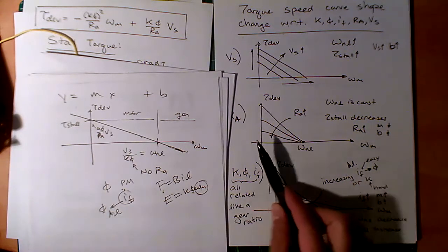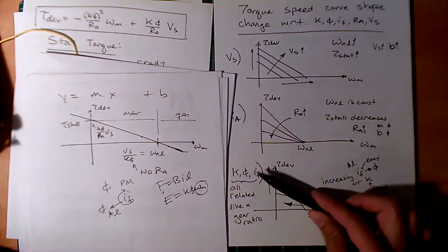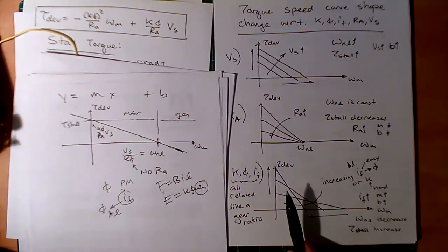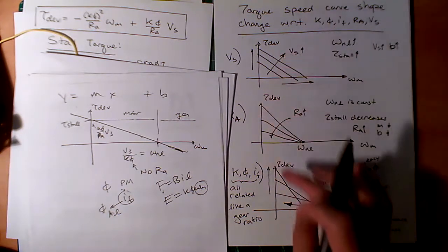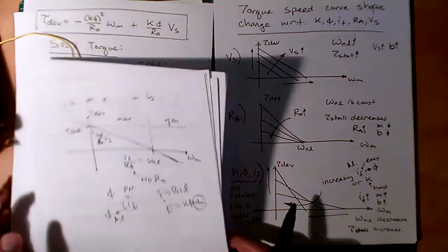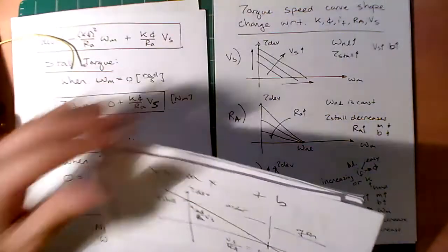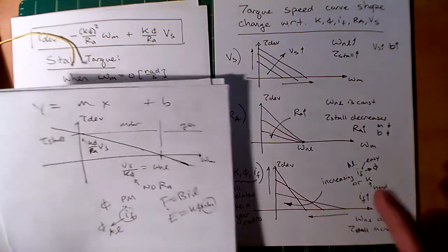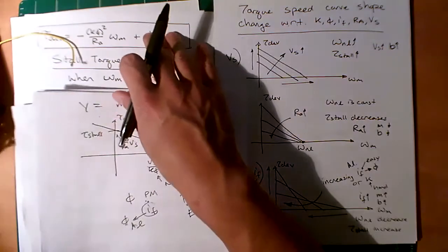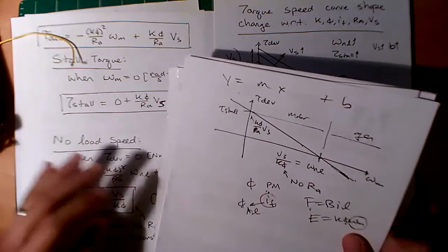You get this kind of gear ratio, right? And what does the gear ratio do? It trades torque for speed. And that's exactly what's happening here. You're trading torque for speed, okay? So I hope this set of plots here shows you how this equation moves and changes, this line changes, and gives you some intuition about the parameters that can affect the behavior of the motor. Okay, and what I also hope is that the theory, the mathematical theory, physical theory, is matching with your physical intuition about what's going on.